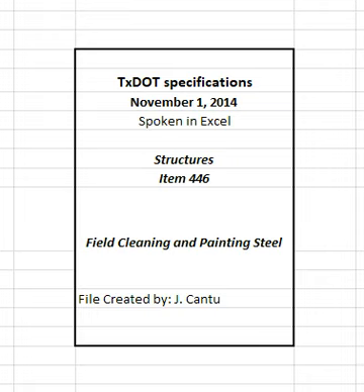Remove all hackles, splinters, weld spatter, sharp edges, fins, slag, or other irregularities which may interfere with proper paint adhesion to the steel. Remove all steel splinters and hackles raised or evident during cleaning. Reblast areas from which hackles are removed when abrasive blast cleaning is required. Before other cleaning operations, remove grease-like contaminants with clean petroleum solvents or other approved methods.